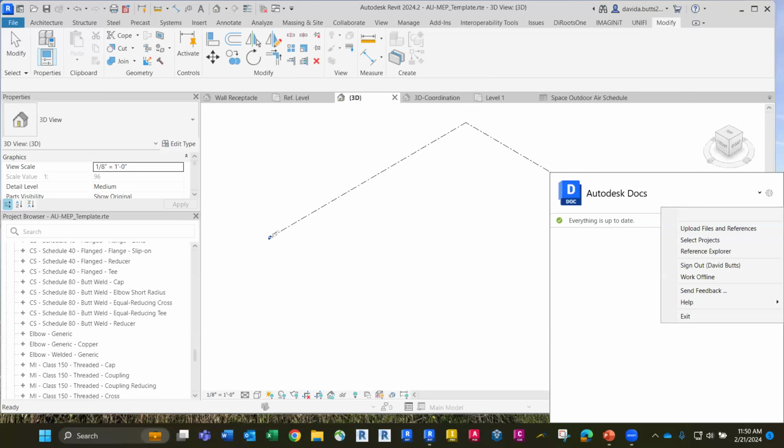I would probably tell you, try out the one for web right now and do your plotting back from a plot list. The projects I have doing that are very stable. They're very fast. I'm not having issues with data shortcuts at all. Several guys, their stuff has been really clean, so we haven't had a whole lot of problems. The only time is when we go back to that legacy XML file that's pulled from a local drive. That one still has a few issues.